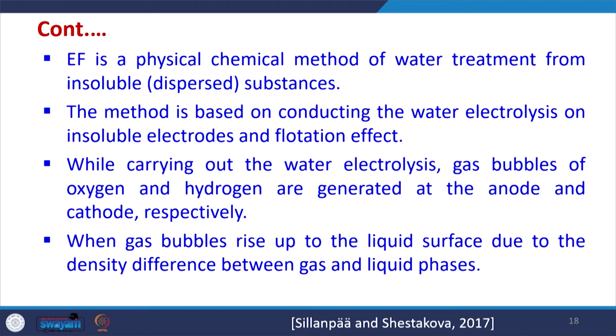Electro-flotation is a physico-chemical method of water treatment from insoluble dispersed substances. The method is based upon conducting water electrolysis on insoluble electrodes and then using the flotation effect. While carrying out the electrolysis, gas bubbles of oxygen and hydrogen are generated at the anode and cathode respectively.